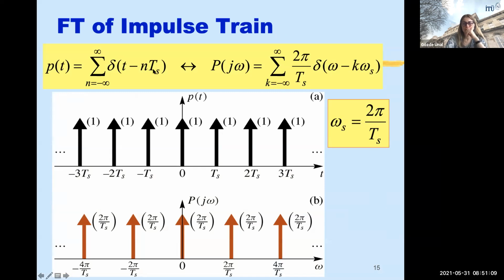And from what we've derived before for a periodic signal, the Fourier transform is shifted impulses, right? And they are actually shifted to multiples of the harmonic frequency. Here it's the sampling frequency, times a_k. Remember, it was 2 pi times a_k. That's why we have 2 pi over Ts. So guys, I hope it's clear.